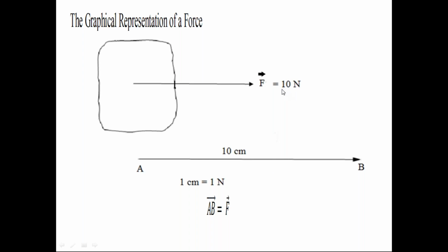10 newtons. So in order to select this length of the straight line, I am using this equation called scale. I am using 1 centimeter length of straight line is equal to 1 Newton magnitude of the real force. This is called the equation of force scale. In engineering graphics or engineering drawing, you might have studied these scales, so you can easily understand this.